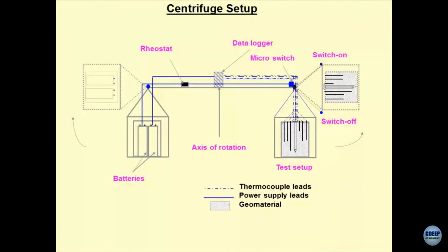And for batteries, we have used another bucket and we have used them as counterweight. This concept took me 3-4 months to realize: rather than keeping the batteries separately and creating another counterweight, we can use the batteries as a counterweight. But the problem is, when the centrifuge is in spinning condition, how would you pass the current through the sample or through the thermal probe.